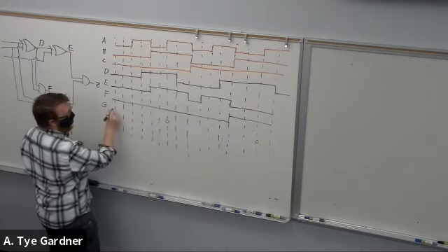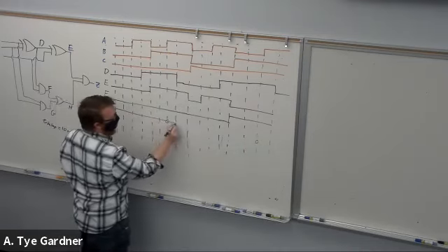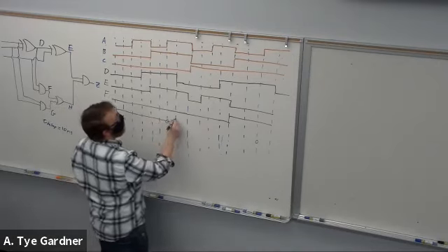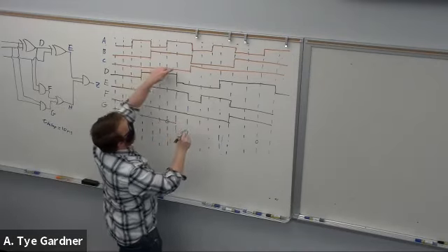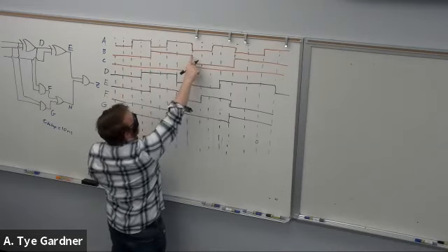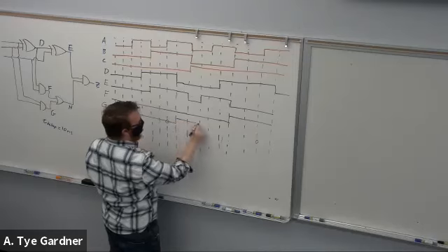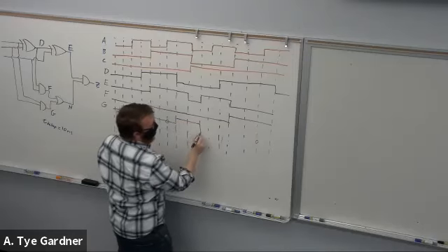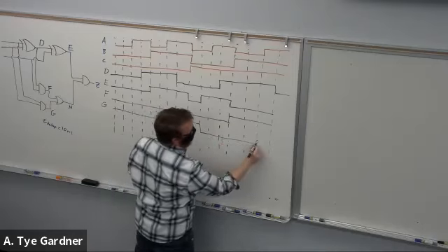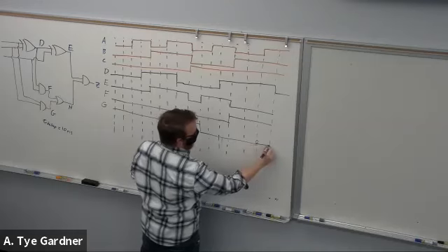So we're false, then true after a 10 nanosecond delay, and now we go back false because it's an AND, with a 10 nanosecond delay. And then we're false all the way until that 10 nanosecond delay becomes true.